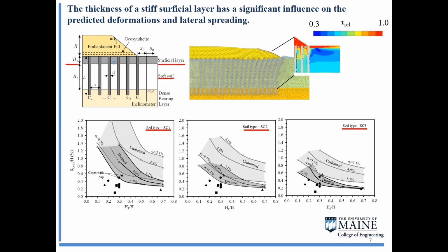So this drain condition is supported by our own investigations, including in the field and numerically, as well as consolidation settlements and pore water pressure measurements in soft soils reported by others for these systems. Okay? So while CSE construction is accelerated and there's no significant delay period or holding period, it is likely closer to the drain condition.